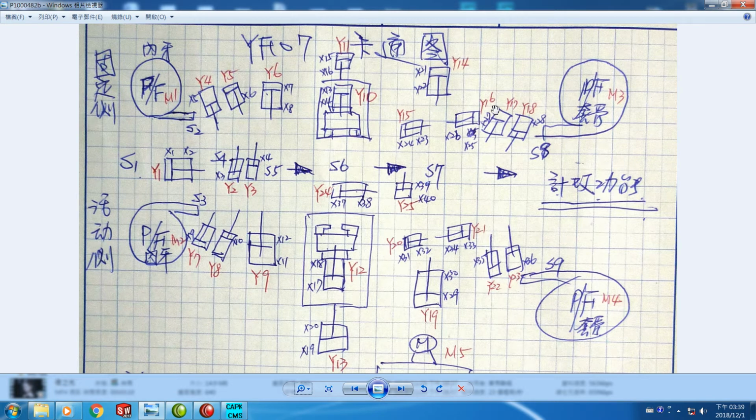Y16 will turn on to push the holder down a distance to form a channel to hold the toolbar in the exact Z position, to let Y14 and Y19 push the outer fixtures to be fixed on both sides of the aluminium bar.